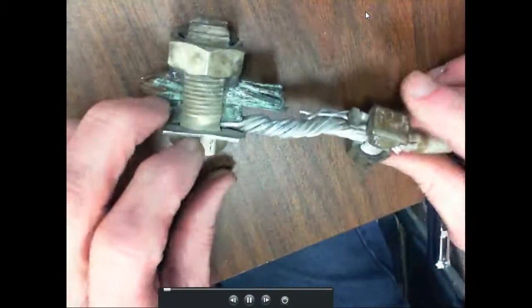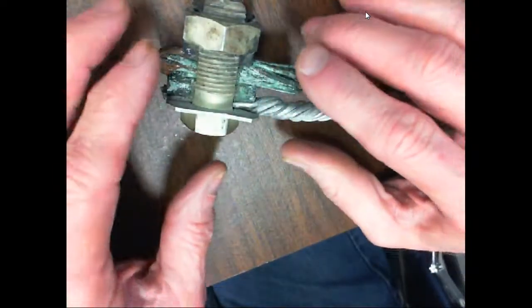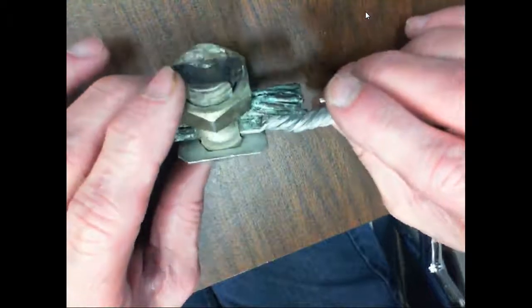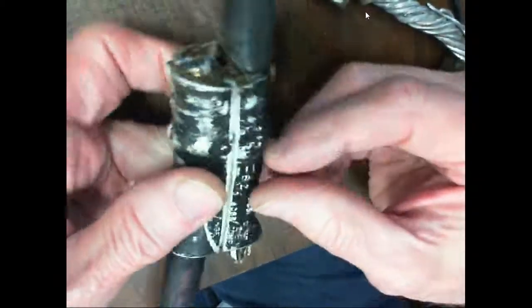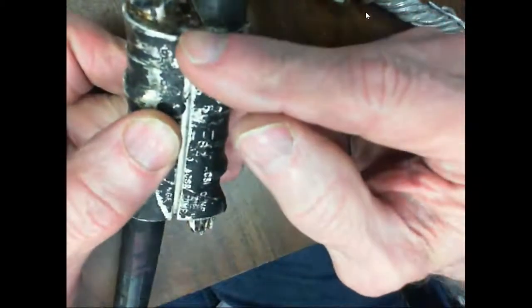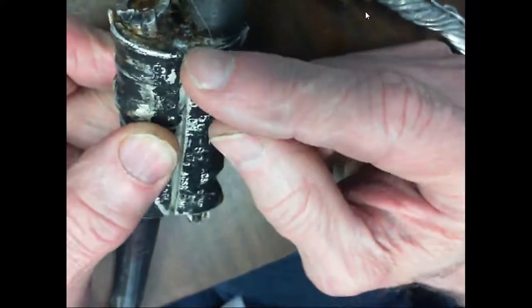So this is mixing copper and aluminum. See, it just broke the aluminum down. The copper just corroded. This is what we call dissimilar metal. You can mix copper and aluminum, but if you're ever going to splice aluminum, this is the crimp splice right here. They've got that antioxidant paste inside here. It looks like grease, guys, and it prevents the aluminum from oxidizing.